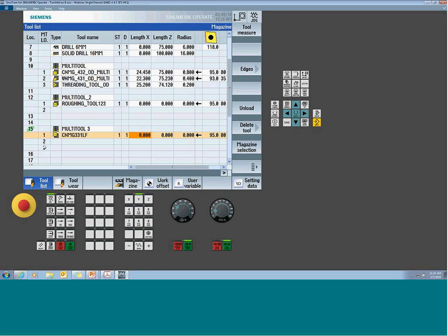When you change it, you pick the tool like you normally would, and it's going to automatically go grab the multi-tool and then orient the spindle to this location number. That's the multi-tool function. You're going to start to see the multi-tools become popular in this type of configuration because certainly it saves tool locations or tool changer locations.